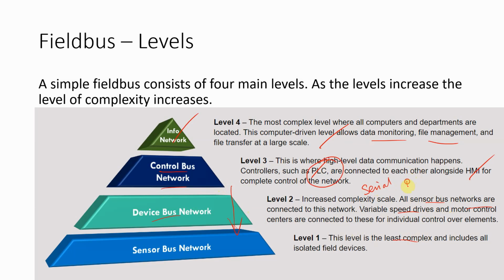Okay, it's either RS232 or RS485. Single drop or multi drop. Level 2 mainly is 485, and if you go to the lowest level it is 232. Serial connection, UART, that's it. There's no point in having this design over TCP/IP because the protocol is not so complicated at the end of the day.